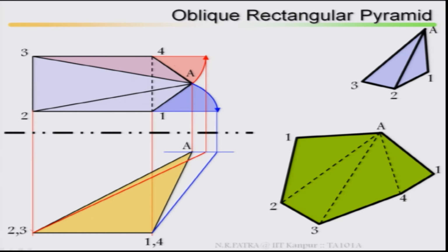That means every time you rotate it considering one of the radii as center, then project it back in the opposite view and measure the true length. So, this is your developed surface of the pyramid. It is very easy if you go step by step.